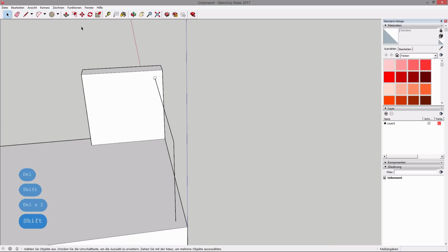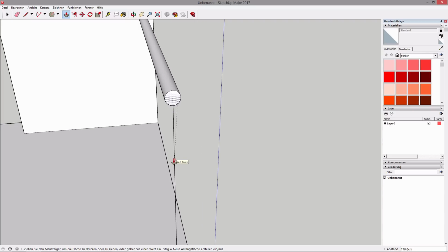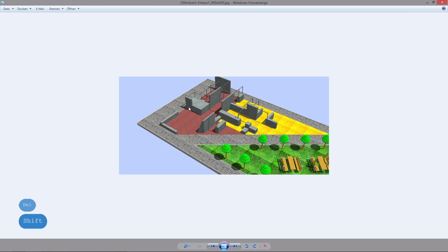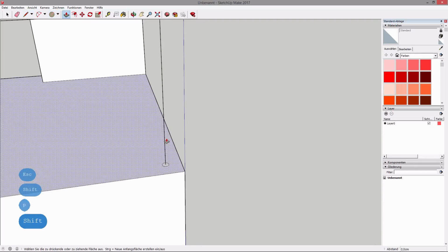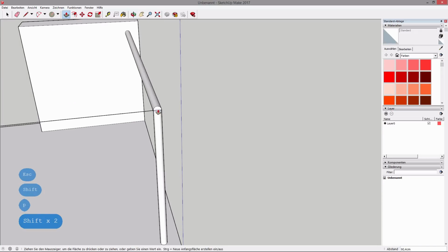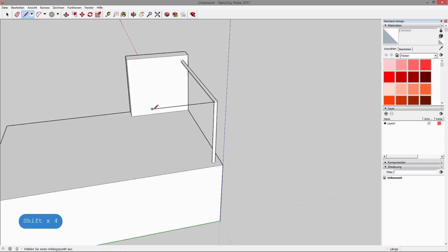We can push pull and now try to focus on the line, and we want an L-shaped bar setup like on the photo, so we click on the edge of our bar setup and track the line along the green axis, so we make sure that the line is green, and we want this bar to be 180. So we can push pull this bar up, fix it there, and grab the line tool again,